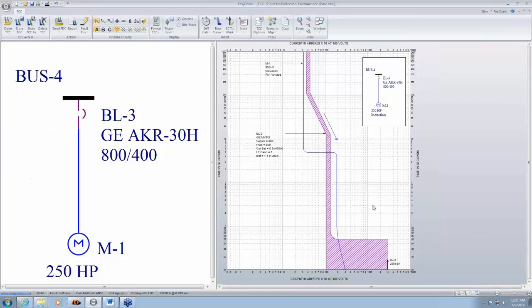So what we need to do is, when we start the motor, the circuit breaker trip curve needs to be on the right side of the motor starting curve. Now, at the same time, another thing we need to be careful about is that this is supposed to protect the motor circuit, this thermal protection. So the long time delay here can be adjusted so that the tripping time is faster than the stall time or the I squared t damage line.